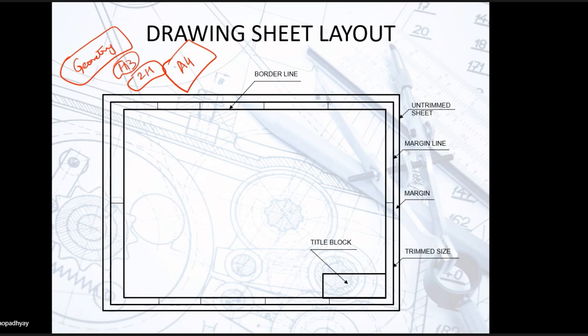So this will be enough for your engineering graphics classes, for your online engineering graphics class, not your offline engineering class. Right. So here you should be having A4 sheet. In your A4 sheet, what you are going to do is draw a very thin border, say 10 mm, 1 centimeter border all around, and you prepare a title box here.